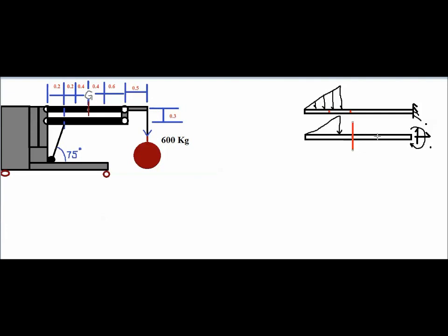What would be the better choice in this situation? See, these are the reaction forces which we do not know, right? When we slice it off from here, there will be other reaction forces at this junction, and then there will be two sets of unknown reactions which will be difficult to solve. But when we know this uniformly varying load, we can replace the whole uniformly varying load by one single force, and we know this force because it would be given in the question.